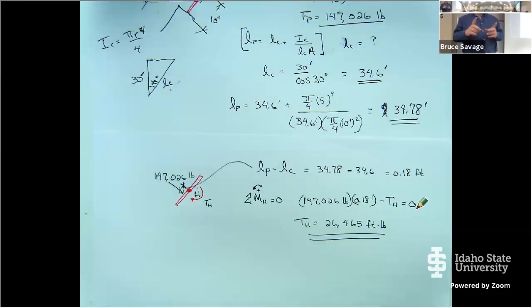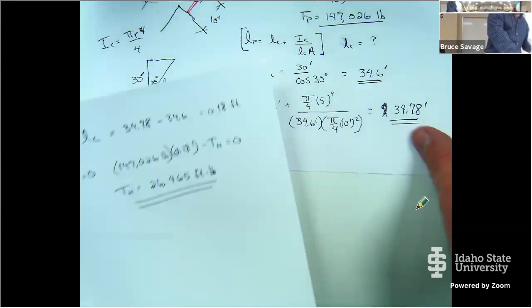So let me back up. For a dam that's not very big, not very tall, and you have a pipe that you may want to use to drain it, that's what we call the low level pipe. It's like, we need to drain this, open that pipe up. That would be a common scenario, but the dam couldn't be very big. 30 feet would be pushing it, actually. Okay. All right. Other questions or comments?